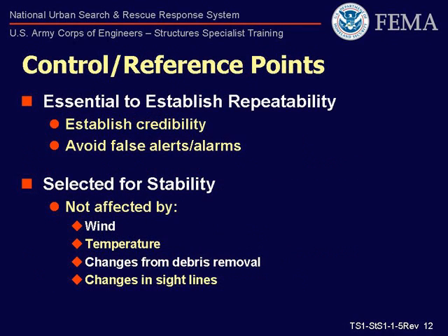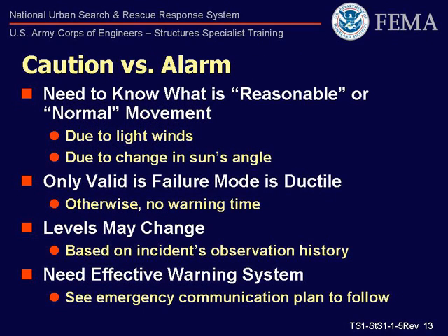The structure specialist must also identify adequate control or reference points on the site that will enable the measurement of the hazard displacement, provide a coordinate system, and enable re-establishment of that system should the instrument be required to relocate. These control points should be as permanent as possible and be clearly visible from several locations. A reminder that the STS must be able to determine the limits of hazard displacement that would be considered safe. By establishing these limits, ductile displacement of a hazard can set triggers for caution by rescue personnel or even alarm.